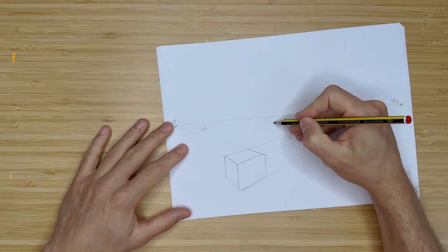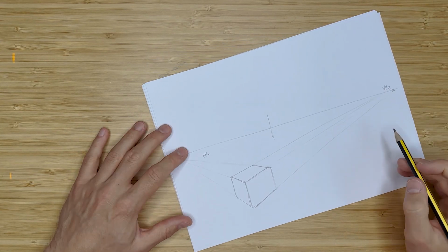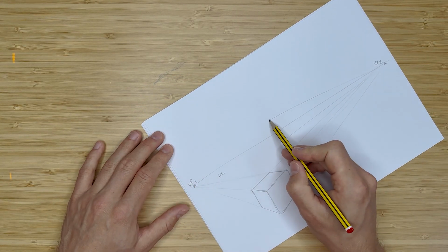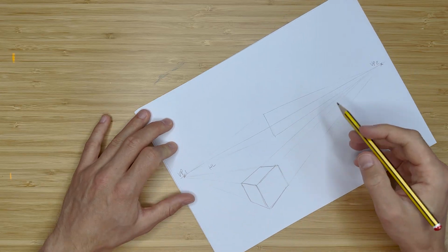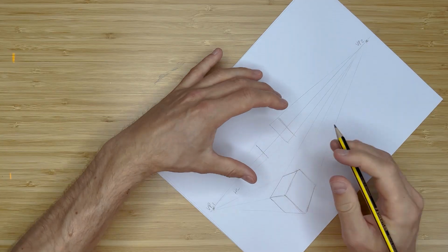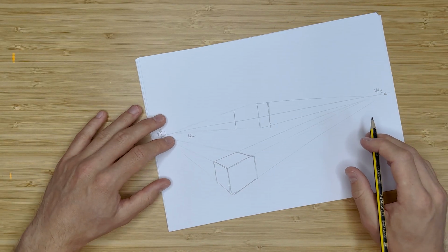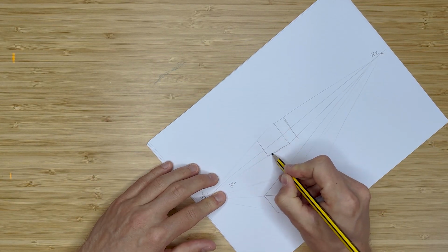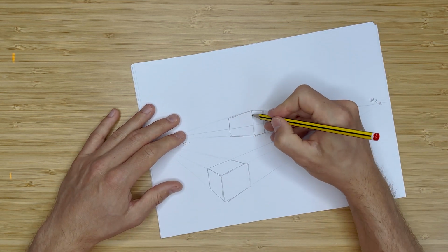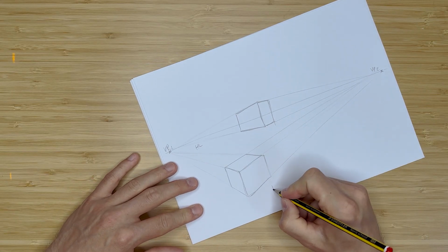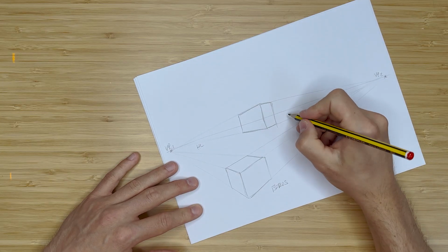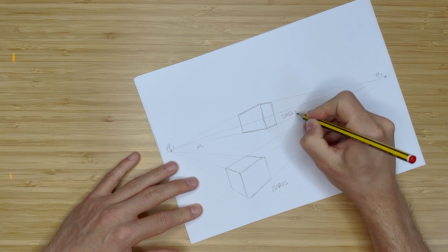You can have one on the street view line. So from the bottom point, we're going to this vanishing point over there, top one to this vanishing point, again the opposite side. Choose our line, so how big we want it to be. So say it needs to be a little bit in that direction, and then we can't see the top or the bottom face because of how the vanishing points are. So we're going to just put those 2 together, and then we have our 2 point perspective from a street view. Okay, so this is known as a bird's eye view. Because you're looking down on it. This is known as a street view because you're at the same level as it.